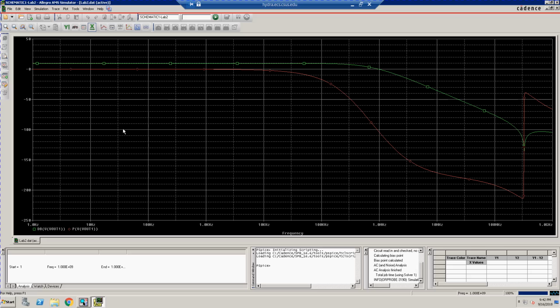So here what we're seeing is you have your voltage gain in green coming across and rolling off out here. Then you have your phase coming across and it's rolling down. And then we have some unique attributes further out in frequency. So that concludes how to perform a Bode plot to this point.